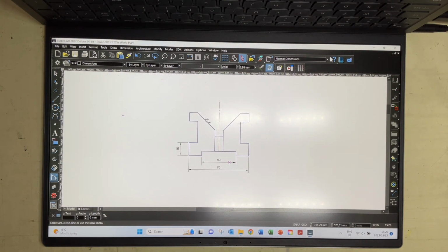Now I come to that line over there and I click on it. I go to that line over there, I click on that, and you can see that little arc that it's drawing. Click on that, and now I can move the 90 to wherever I want that 90 to be. I'm going to take the snaps off, and you can see that it doesn't snap anymore, so I can now place it wherever I want to place that 90, and there you go. I've got 90 degrees shown in that little arc over there.